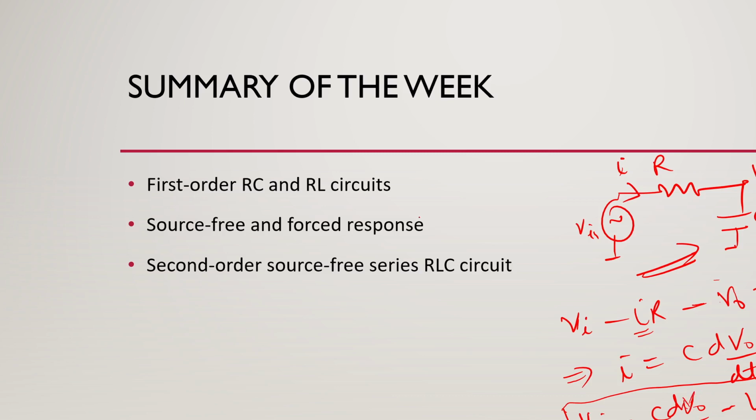That is why we say that this kind of circuit is a first order circuit, because the differential equation that we will get for this circuit will be first order in general. Similarly, a similar analysis can be done for RL circuits also, and you will again get a first order differential equation. We also talked about source free and forced response. So what was the source free response of first order circuits? First order circuit was of this kind, isn't it?